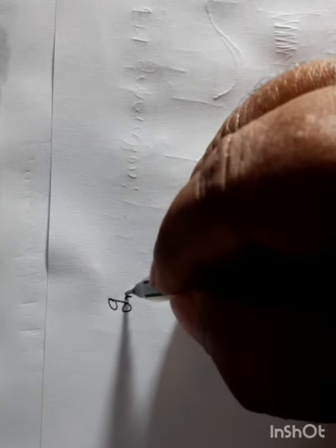And we know that the transconductance is denoted by Gm. Transconductance means the input voltage is transferred to the output as a current. This is called transconductance, denoted by Gm. Conductance is nothing but the reciprocal of resistance. Resistance and resistivity, conductance and conductivity. Therefore, conductance is inversely proportional to resistance. The unit of resistance is ohm. The unit of conductance is mho.